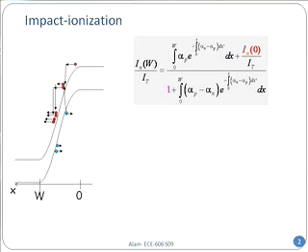And you can also see IN of 0. IN of 0 is the amount of injected current on the right-hand side of the junction. Where is that current coming from? Do you remember that in reverse bias, on the minority carrier side, the carrier concentration was suppressed to 0, right? As a result, there was a diffusion flux, a constant diffusion flux coming out from the right-hand side. So that minuscule amount of current will be the seed of this avalanche, and then it will proceed. So that's the right-hand side, the one in red. IN0 is the reverse diffusion current flowing through the diode, right? And this is something we have already calculated in our previous class.